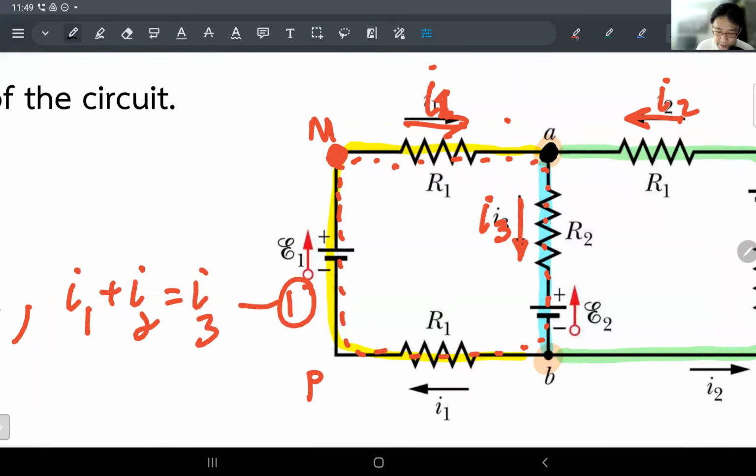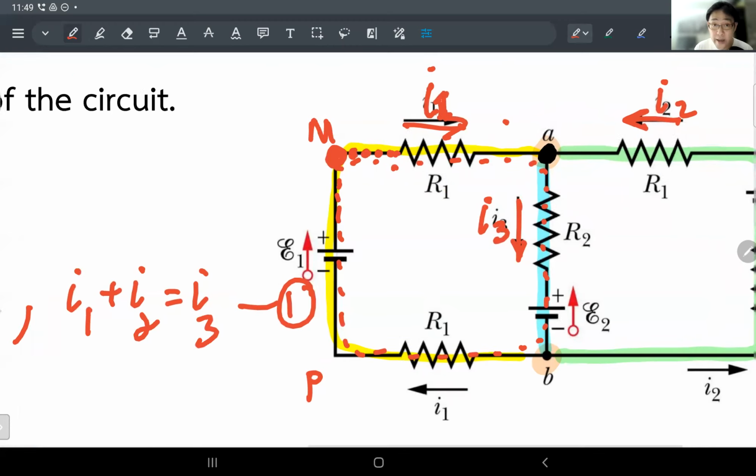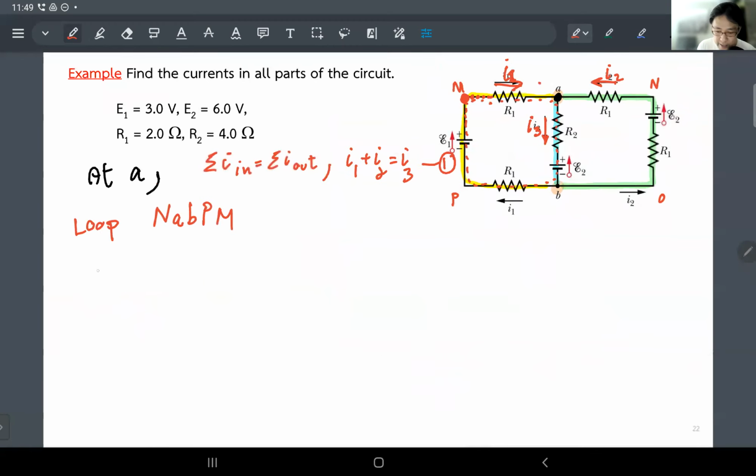I'm just walking. Now I'm phasing R1 with the current I1 in the same direction as my analysis. So I'm going downhill. So I'm saying I'm having a negative I1 R1. Keep walking, guys. Now I'm at A turn. Down along the blue wire.